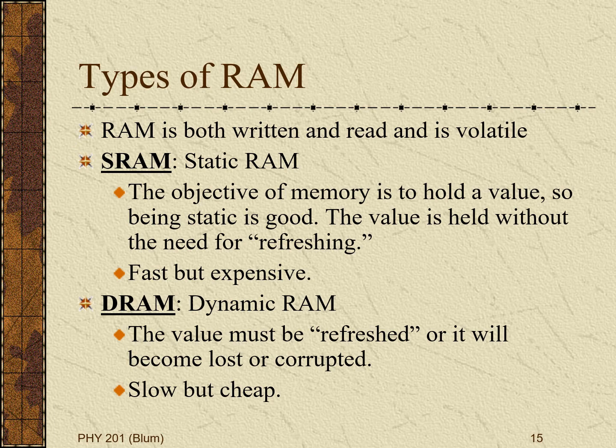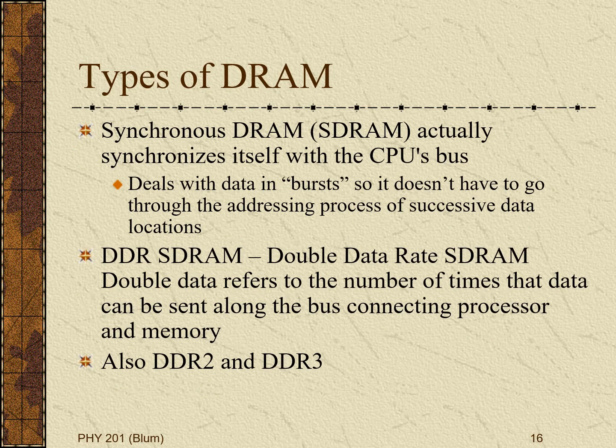Now there's a pretty long history of various types of DRAM, which I'm going to cut to the chase into the more modern versions. So all modern DRAM is known as synchronous DRAM or SDRAM. And synchronous means how the memory works in conjunction with the computer's clock, the processor's clock, and the various buses in the processor.